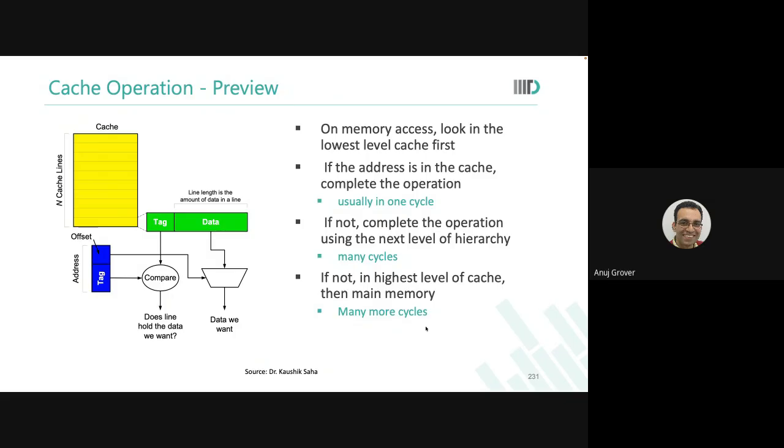Are you able to see this? Which tag is referring to which? Oh, for this you always ensure that whichever address you are writing into a particular location, that content has to be in the same word location in the other memory. So you can actually, instead of keeping two memories, instead of a 32-bit L1 cache, have a 64-bit L1 cache, where all the 64 bits are together.